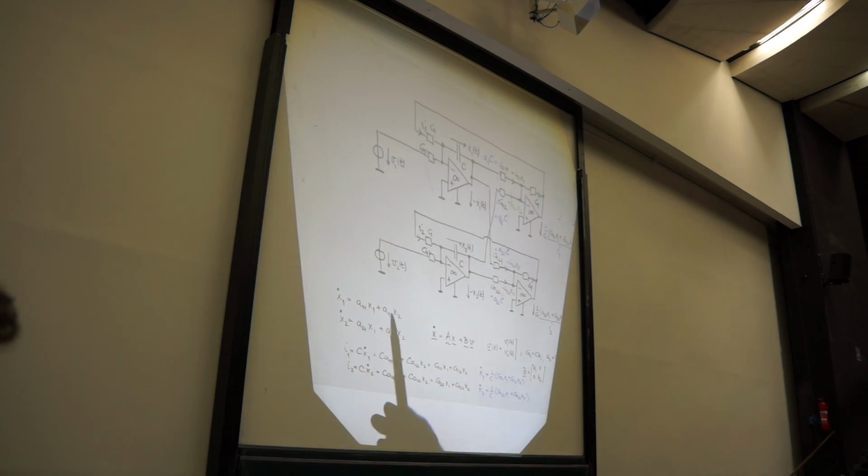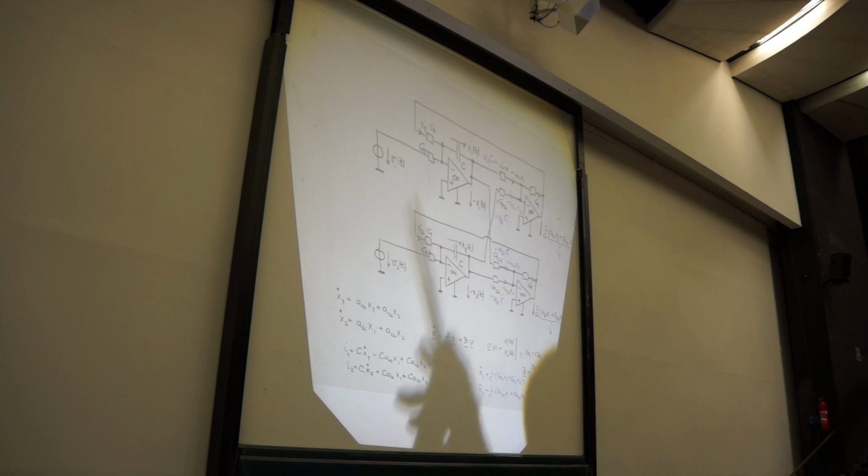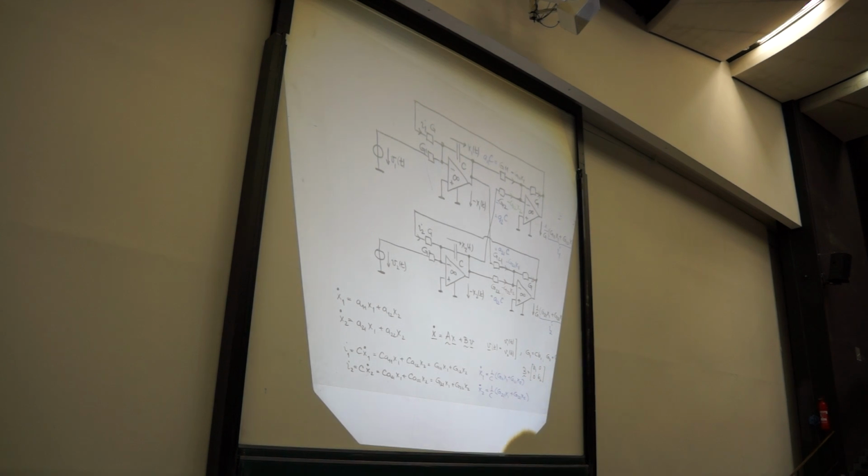So if the matrix capital A with these 4 entries is given, we simply take these entries, multiply them with the value of C, which we have chosen freely, and get the conductance values. Invert them, and you have the resistance values you have to buy and solder into the circuit to actually produce these equations.